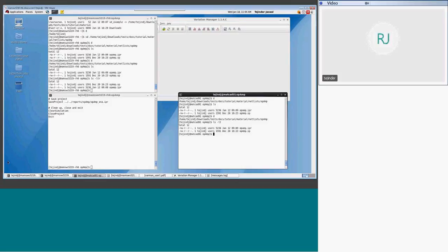So I'm not sure how much you're familiar with Variation Manager, but basically, if you have a design that can run SPICE with a given statistical model, you can do analysis in Variation Manager: Monte Carlo, variability explorer, high sigma, performance and yield analysis.